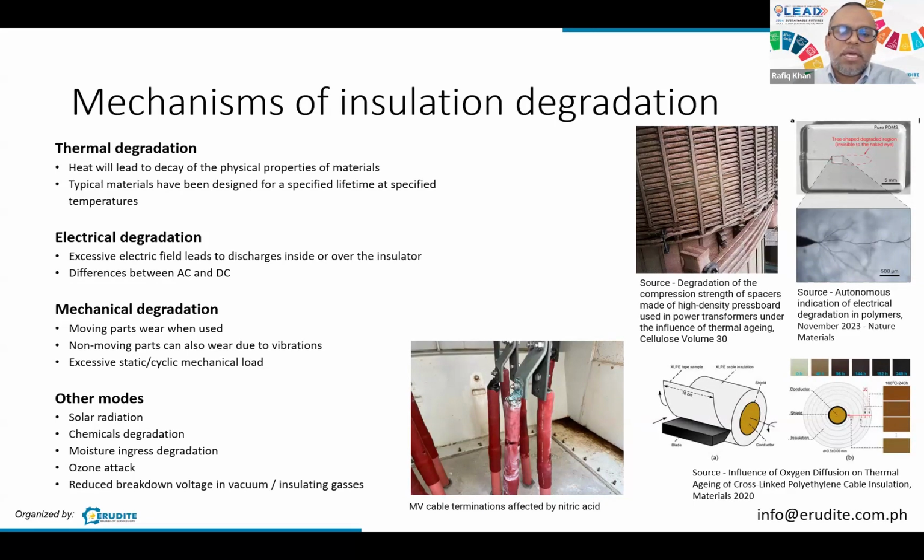Something that can be put as an example is an XLPE insulated power cable. During the manufacturing processes, these cables are degassed, where methane is being pulled out of the XLPE, cross-linked polyethylene. You don't want to have gas bubbles forming inside these cables. So during manufacturing, they put these cables into ovens, which are about 70 degrees C. After manufacturing, they come to about ambient temperature, and then they are put in service.